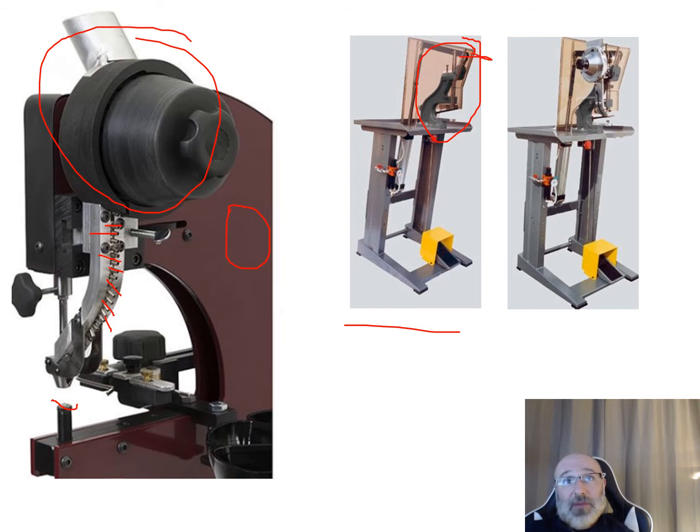But now rather than having the handle coming out the front that we're pushing down on, we come off the back, come down here to a pneumatic piston with, and this is the beauty of this too, a pressure setting. Because with these types of rivet machines, you're manually addressing the height to get just the right amount of compression on there, and there's not really a feedback sensor built into those. So you're just figuring out what that height is, setting it just right, then stepping on it to the right distance every time in order to achieve the right amount of pressure, not compress too much and split the material, or not go far enough and not round the rivet over enough.